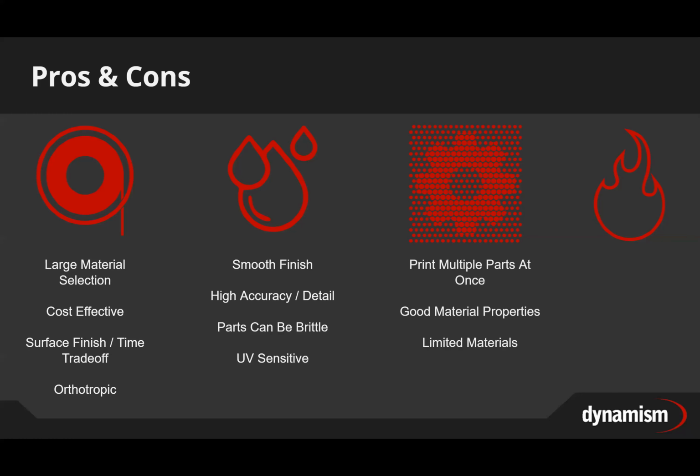And then lastly, metal. The great thing here is no machine labor required, as well as no tooling. But the cost and time can really add up. There are limited materials, and startup costs can get high on the metal side. Some of the materials out there right now are 17-4, 316L, H13 tool steel, 4140, and copper, and they are adding to that continually.